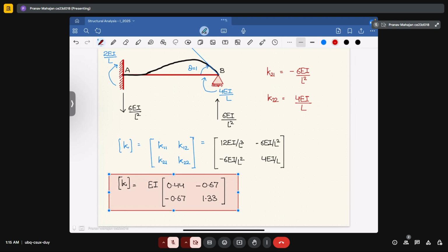But when you have an additional compatibility equation available at the middle of the beam or at any point of the beam, like the provision of an internal hinge, that provides some additional compatibility equation to solve the beam. So that will also act as an available equation. In that case, when you have one internal hinge, your number of available equations will become equal to 4.